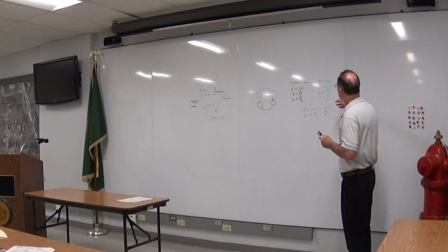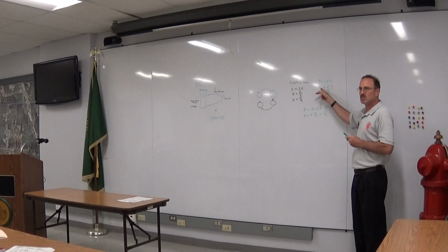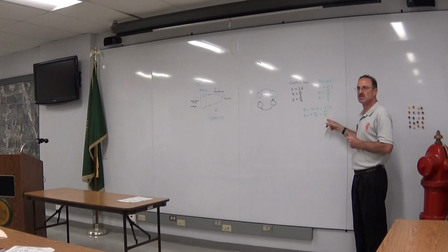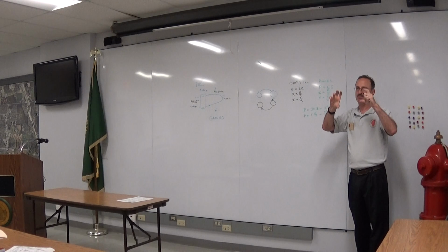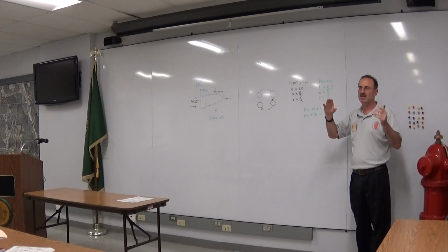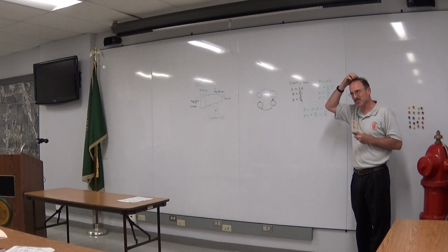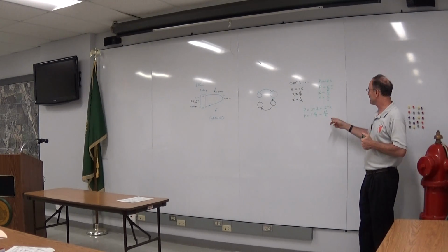So let's go back to Ohm's law and the power law. Substitute heat lost for power, okay? And we have a fixed resistance in a piece of wire going down the street. Can't change that except by going to bigger wires, and that becomes expensive, very expensive, and hard to do, and very heavy, and lots of problems.